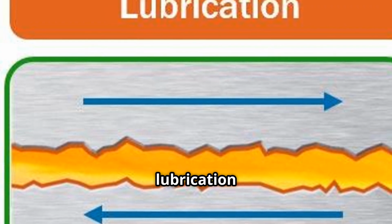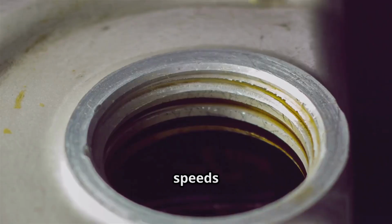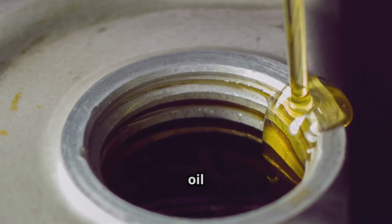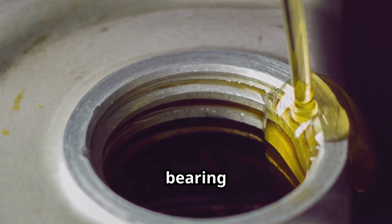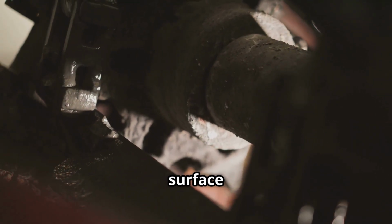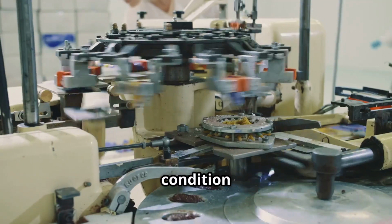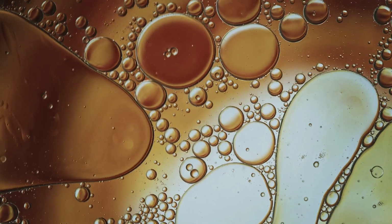This lubrication regime condition occurs after a machine has begun to rotate and the speeds and loads are such that a wedge of oil has been formed between the shaft and bearing surfaces. This wedge of oil lifts the shaft away from the bearing surface, so there is little risk of asperity contact. This is a desirable condition to avoid friction and wear.